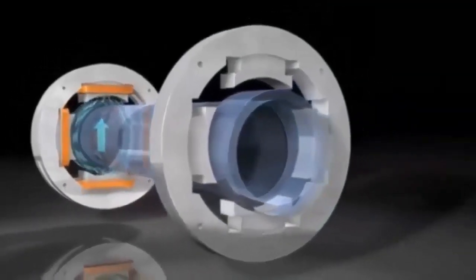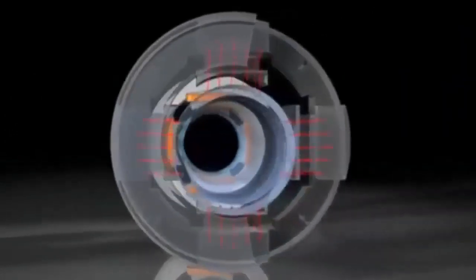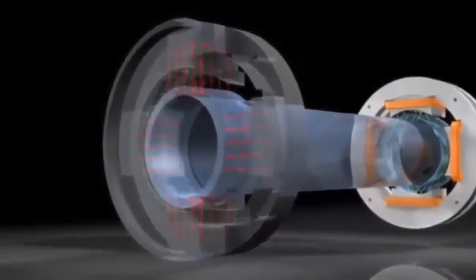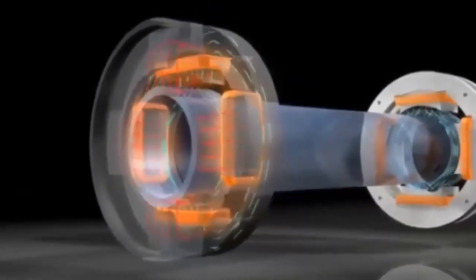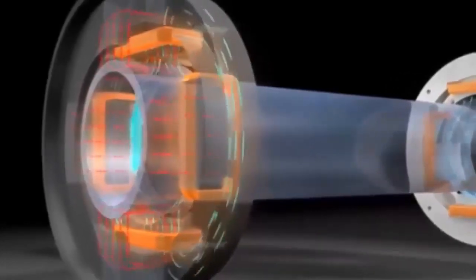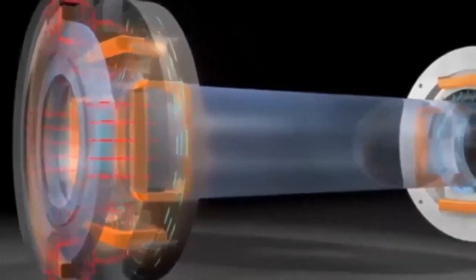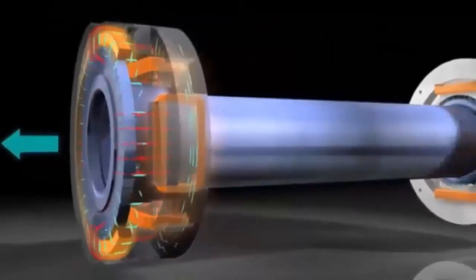Also, the use of magnetic levitation compressors has been extended to smaller brands. This type of equipment stands out quite a lot in cooling thermal load. The highest performance will be observed when the load is below 70%. It is recommended when it is believed that the chiller will work in a considerable range of time at a load of less than 70%. This type of system basically consists of two bearings, a radial and an axial type bearing, to be able to correctly carry out the elevation of the equipment.